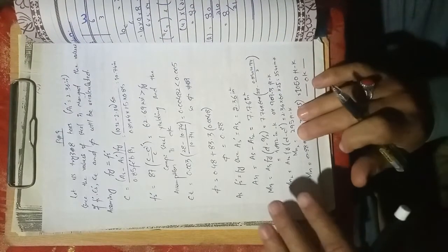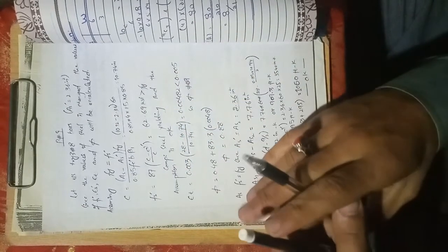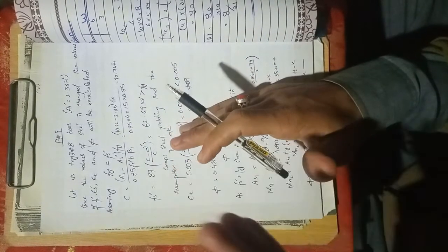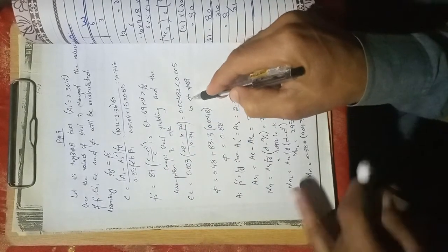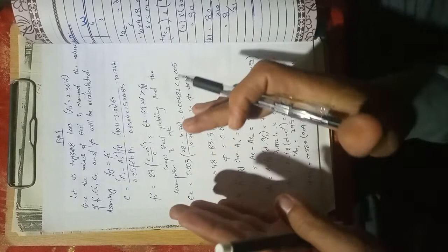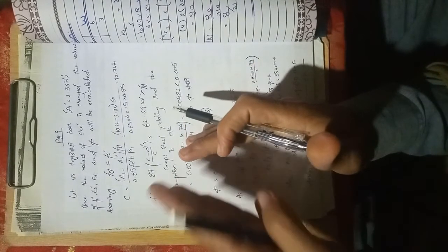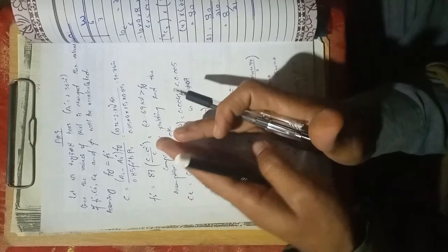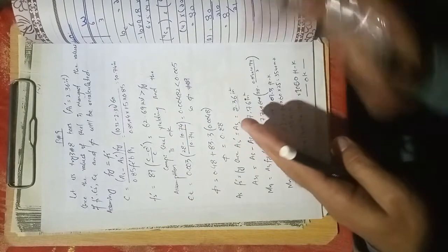Right here you see, this is the calculation that you have to do to ensure your ductile capacity, ductile behavior, and you have to ensure the value of phi. This is the complete procedure of designing a beam, right? Either it is a doubly reinforced beam, a T beam, or a slab. Okay, you have to check these things if you want a proper design.